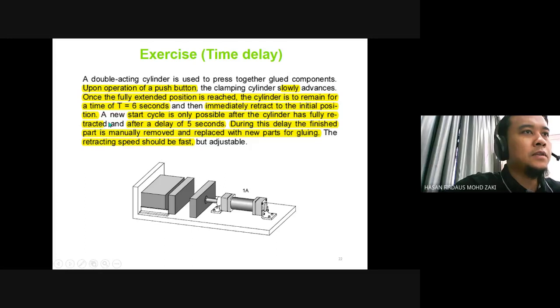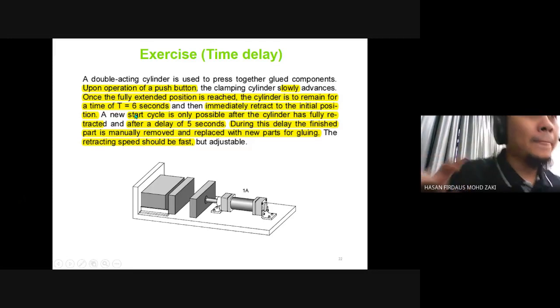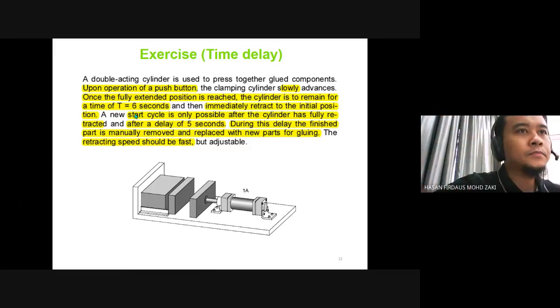This one up until here is the same, and after a delay of 5 seconds. So this is the addition. Not only does this one need to be in full retraction to start a new cycle, but you also need to wait for 5 seconds. Only after that can you start a new cycle. You can press the push button and the new cycle will start.